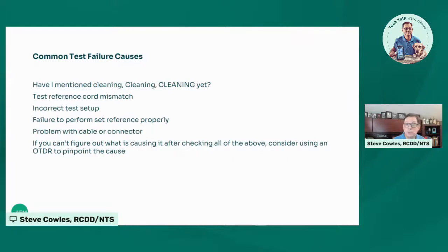You could have a problem with the cable or the connector. So if you've installed it properly, it's been terminated properly, the odds of a problem with the cable or the connector go down based on that, but it doesn't make it impossible. So you could have a problem with the actual connector. You could have a problem with the cable itself. Maybe it was damaged while it was being pulled.